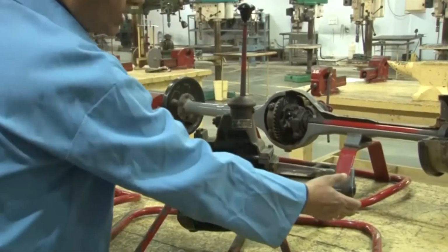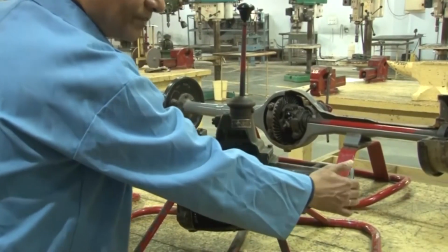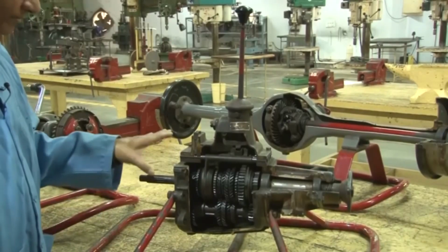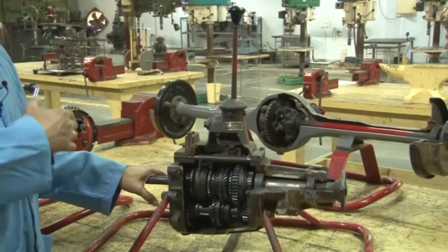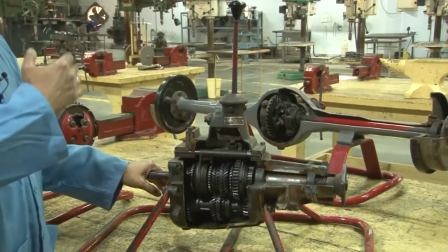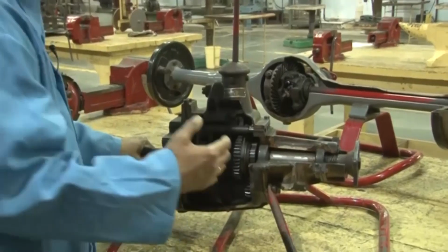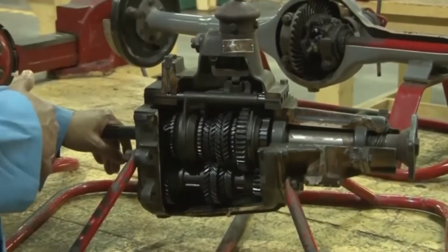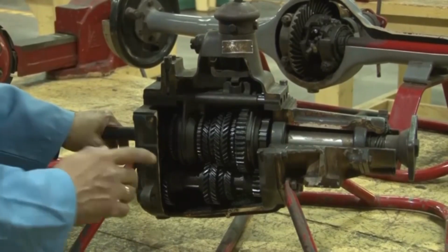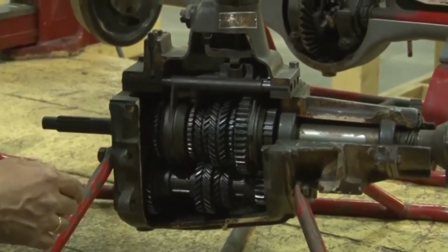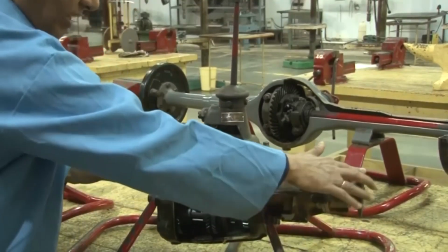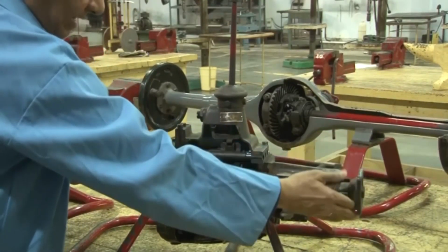So, this shaft is the input shaft, and this is the output shaft, meaning from here the transmission goes to the wheels, wherever the transmission is required. It may be the rear wheels, or sometimes the front wheels, depending on the type of the car. At this moment it is in the neutral position. If you rotate this, you can see that the output shaft is not rotating because it is in neutral.